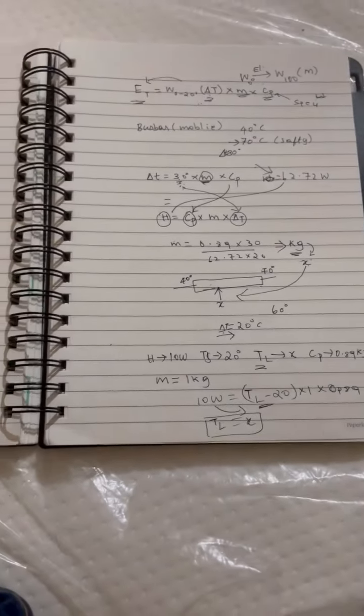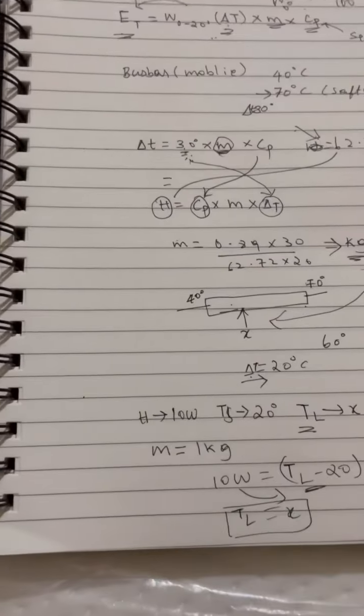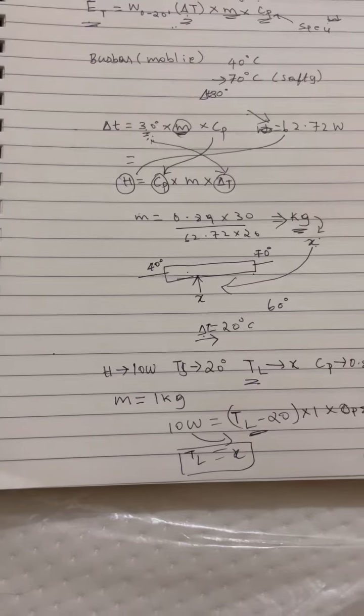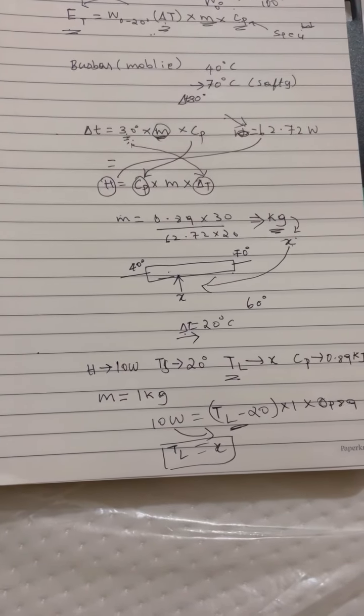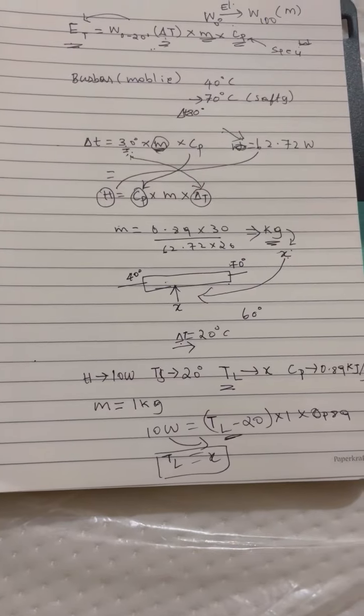So with this same formula you can either calculate the bus bar, or you can predict how hot your system is going to get. It is as simple as that. So we have understood from the formula how much temperature it's going to rise, and how much mass your system needs to have in order to have a particular temperature rise.